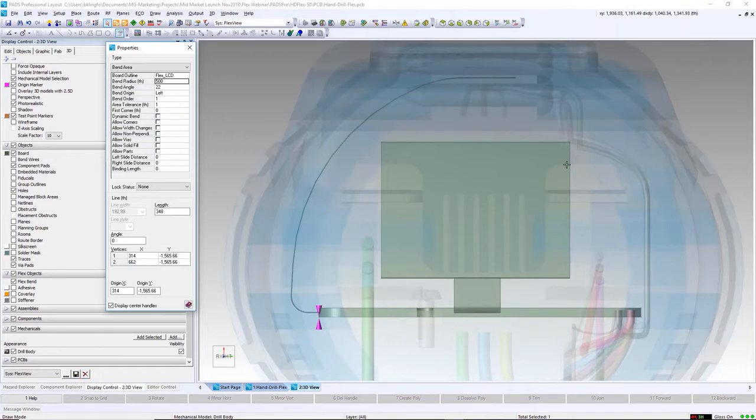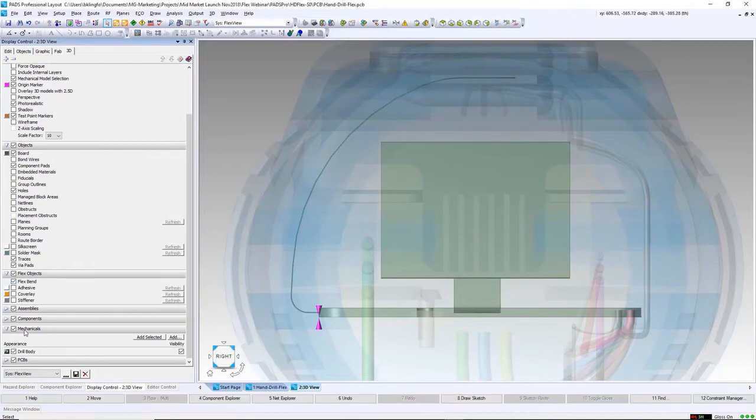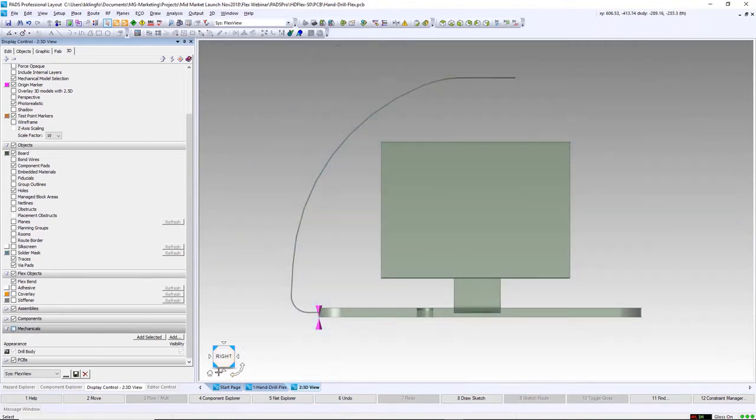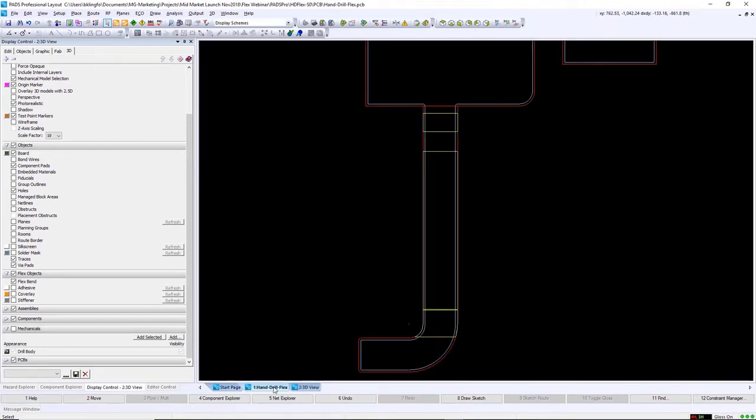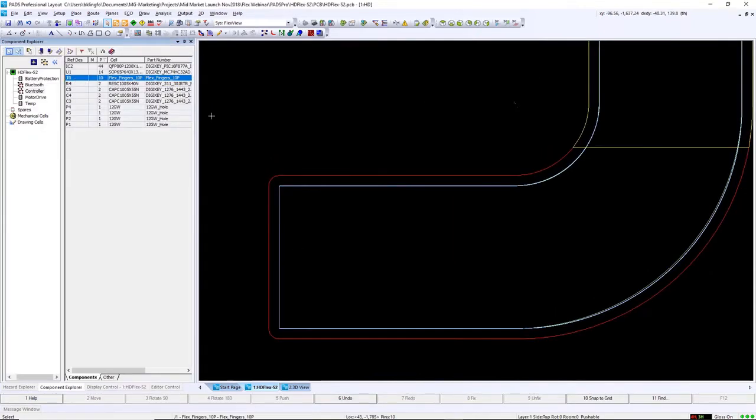As you can see, using 3D visualization dramatically cuts the time it takes to create our base geometry for this design. Yes, 3D MCAD tools have the capability to bend objects in view with the enclosure model. However, there's no electrical or manufacturing intelligence when designing flex circuits outside of a modern ECAD tool like PADS Professional. Now that we have the board outline created properly, we can start placing parts on the design.